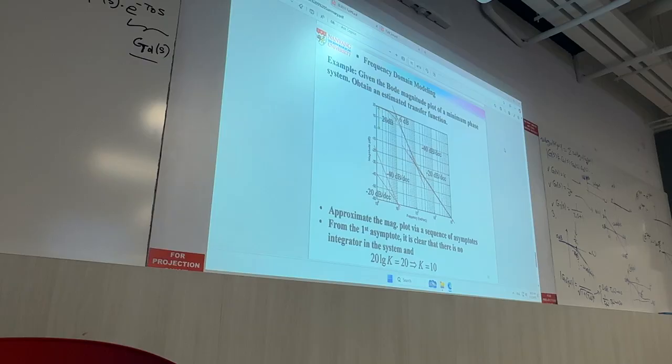So you get all this, and you plot them on semi-log paper. At one frequency, you get one magnitude point. On the phase, you get another point. Then you change the frequency of the input signal, and you are going to get many values. So you are going to get these Bode plots. Correct? So once you have the Bode plots by experiment, the question is, are we able to derive the transfer function?